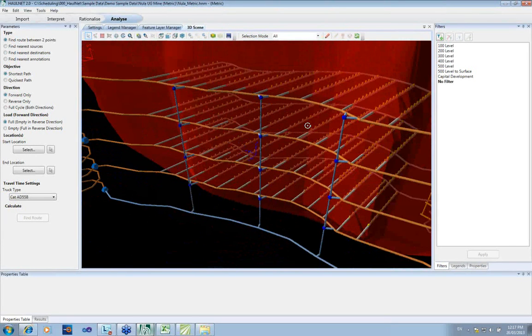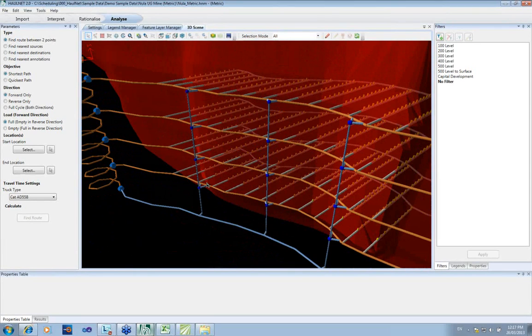So here we've had these blue vertical lines here are our ore passes and tip points just here. We can then move on to these extraction drives here, where we can see our stopes have been shown here. So that's the 400 level, and that's an individual stope, all imported as sources into the model.